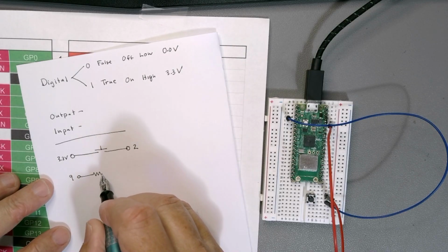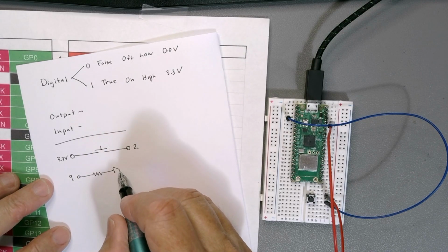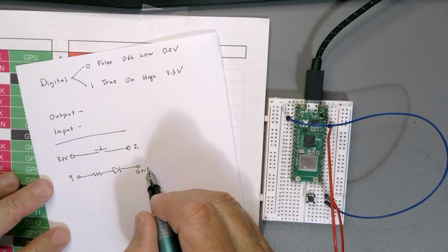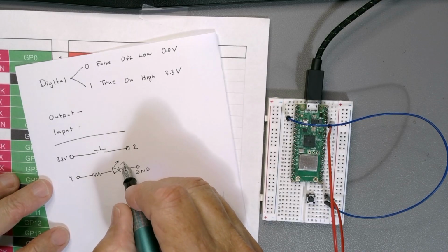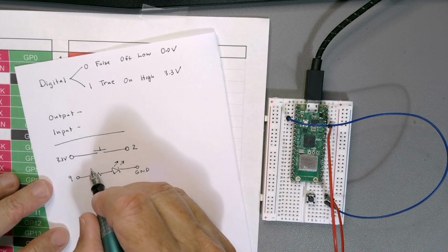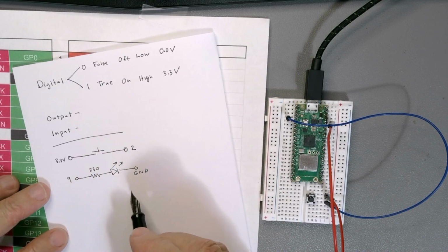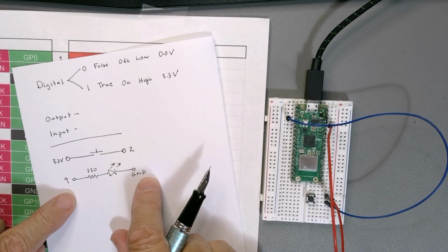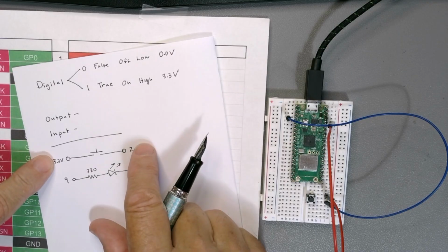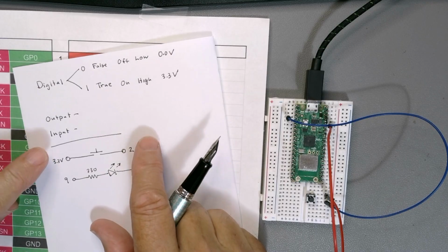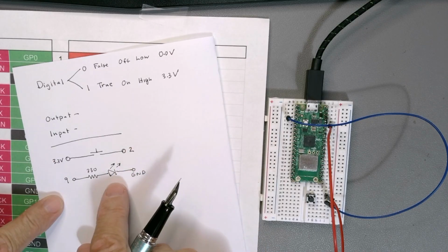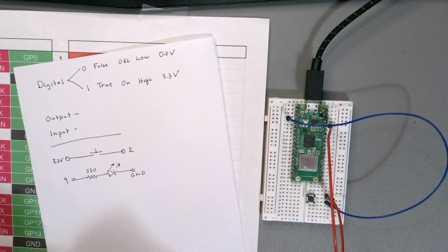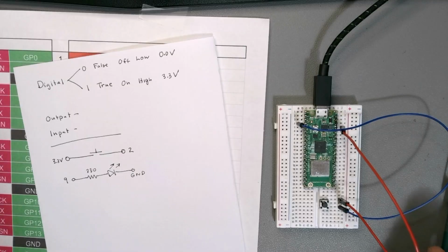Pin 9 is what we were using, and then an LED, and then ground like this. So there's my LED, and this was 330 ohms. So here's the idea. I'm going to have two separate circuits, and I'm going to use this circuit to tell when the button is pressed, and based on this, I'll change what the LED does.